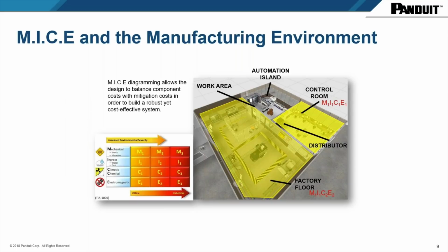The only thing we need to worry about in that space is some emitted radiation. So there could be some power systems running in the ceiling and conduit and other places that can affect communication. So therefore, cabling in those spaces has to also be considered to look for where we have emitted radiations. And as you identify those different areas where certain power systems are being run, you will then start elevating the hazard environment for these elements.